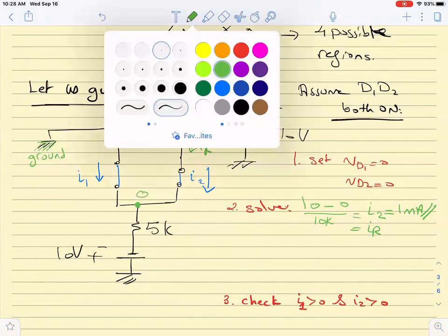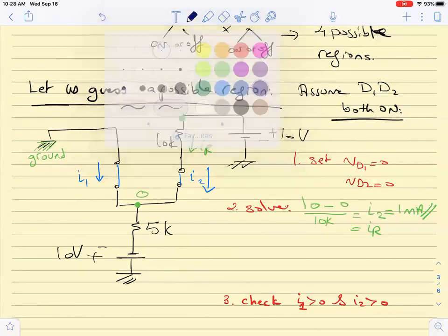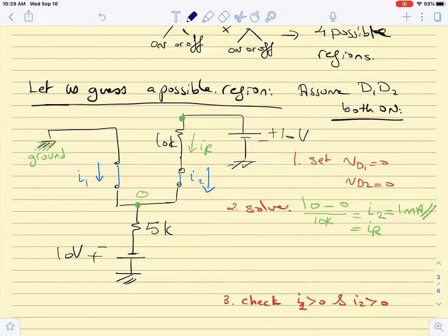We know that the voltage... I think we can do KVL for the left half, since we have 10 volts and a 5. Be careful that the current is falling between a 0 and a 0 in this case, right? We need the resistor, otherwise we can't do KVL, right? So the voltage is 0, so I cannot know, because 0 times the resistor gives 0, and I won't be able to solve it. So now let us do KCL on the node.